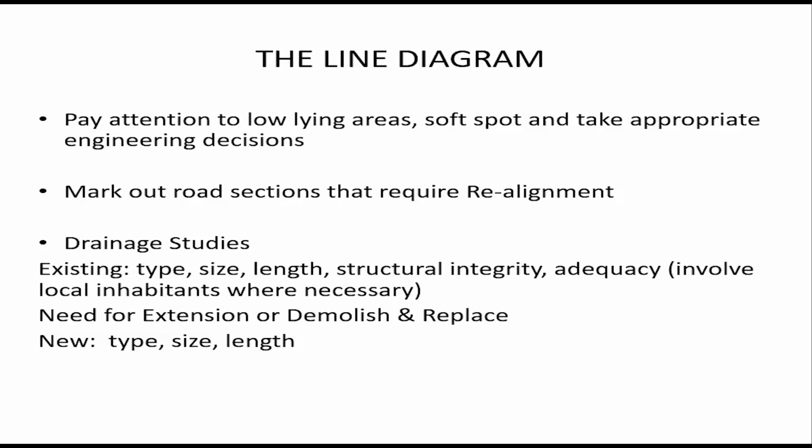And then also, you should be able to go into the culvert and see the watermark. Sometimes the watermark will be very high, and that tells you that this culvert may not be adequate. Then you also need to see if there is a need to demolish, extend or replace the existing drainage structure. And then you have to look for areas where you need to install new drainage structures.